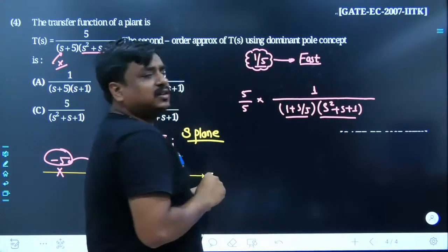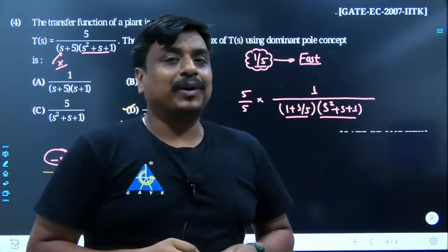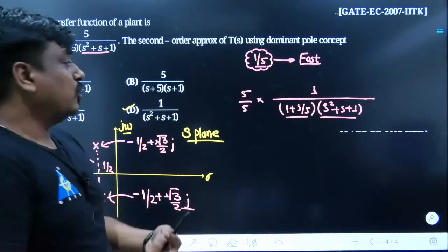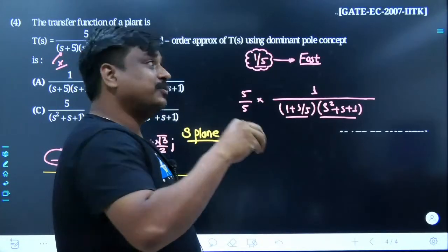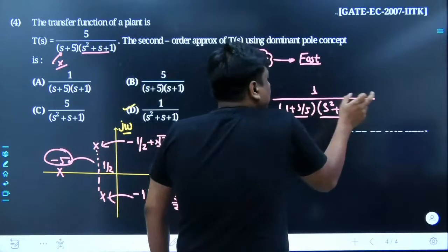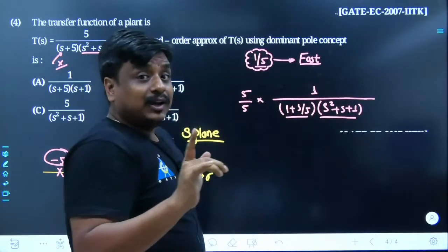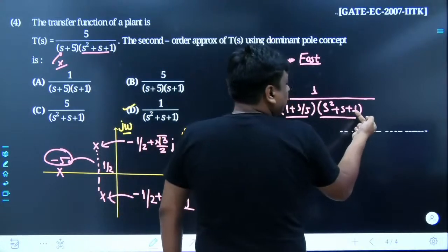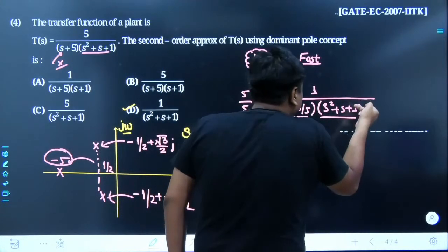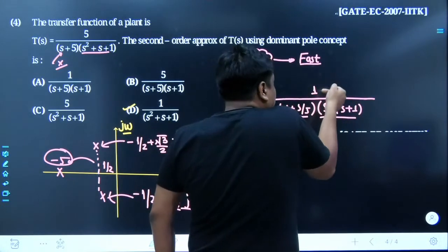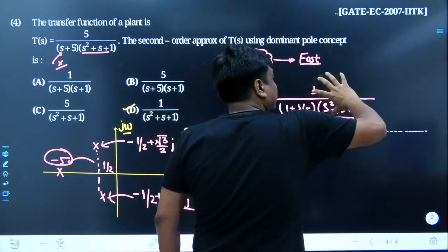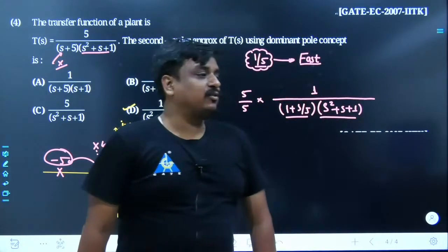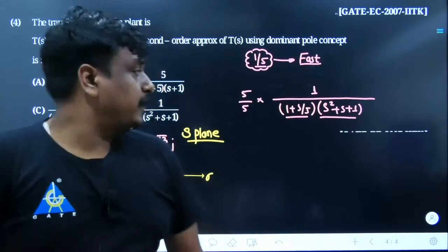So many students think a lot, sir, what does it mean by the standard form of the transfer function? In the standard form of the transfer function, we ensure that if s is fed 0, omega is fed 0, the individual terms are going to create only and only what? Unity. Now people would also say, sir, here I can have 4. My dear friend, here you can have 4, but if it is 4 over here, in standard form, the 4 should also be over here. So this factor would always lead to 1. Could you really understand what exactly I wanted to communicate through this thought process?